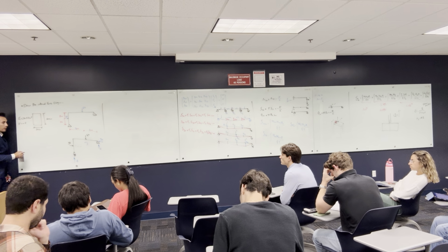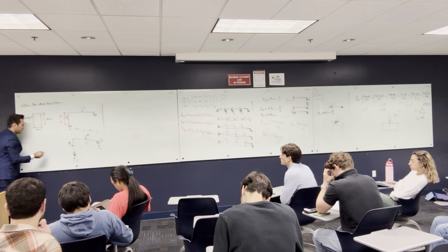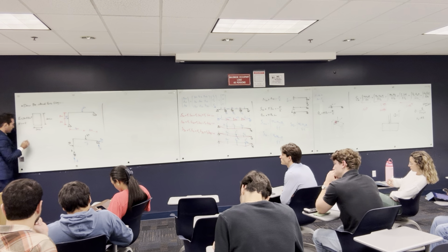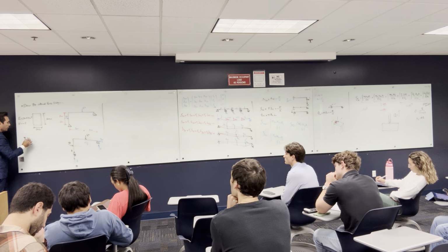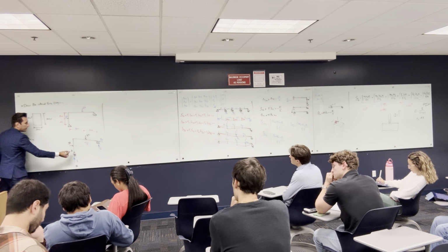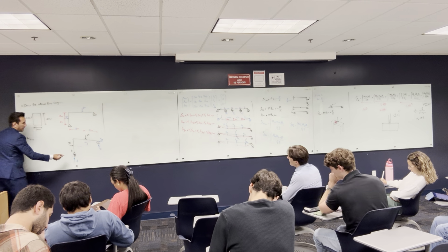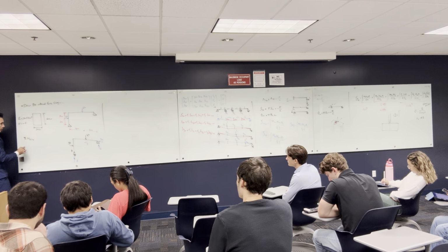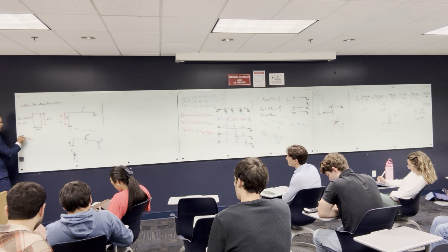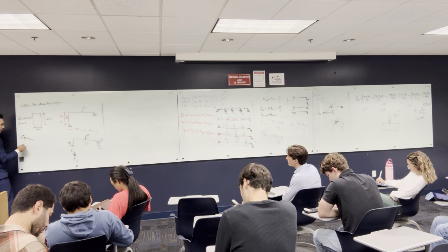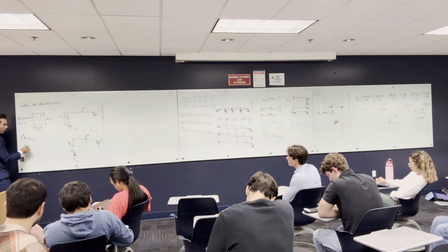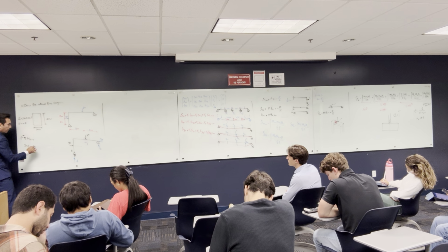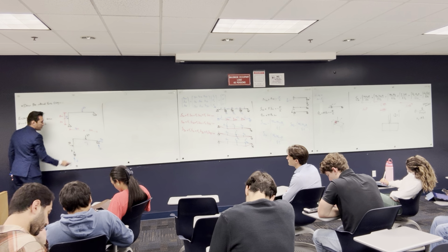the safe way to do it is to get the moment at A. Like let's say you are gonna get the moment at A, summation of the moment at A should be equal to 0. So getting the moment at A, we don't know what is the value here in the reaction, so I'm gonna assume that the positive that way, so 3 multiplied by 2, plus 6 multiplied by 3, the moment of this, minus.